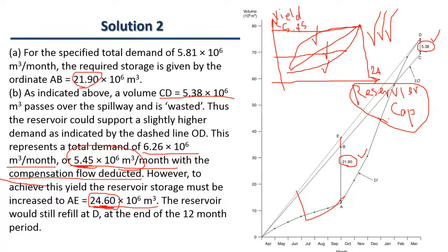Remember I discussed the sedimentation. One of the ways that the operators can release the sediment from the dam is by releasing or opening the gates, or the bottom outlet. The bottom outlet is one of the gates in the dam, used at the time of the flood. Why? Because at the time of the flood, a lot of sediment can be suspended, and it is the best time that you can release the sediment, get rid of it, and benefit the environment as well. So nowadays, please pay attention.